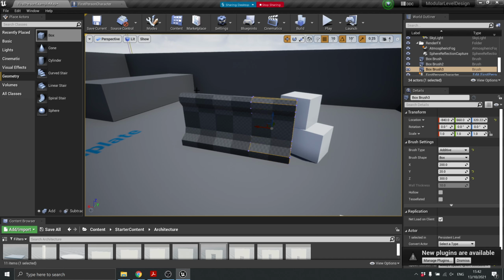You can, yeah. So you can do that, and that's one way to do it. The other way is to just use two of them and connect them together. The one thing we wouldn't want to do is extrude it, let's say to 500, let's say 1,000 long or something like that, because your texture is going to get stretched a bit. So sometimes it's more useful to have smaller bits that we can change and tweak. We can have a variation that's like panel damage, panel clean, panel graffiti. You know what I mean? And then you can put smaller panels together to get more variety. If you ever see repeating textures in games, sometimes you want to break that up a little bit.